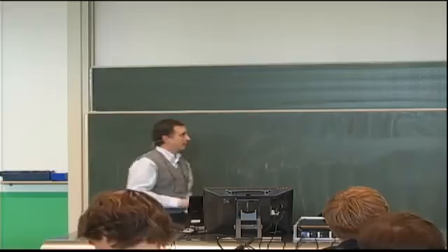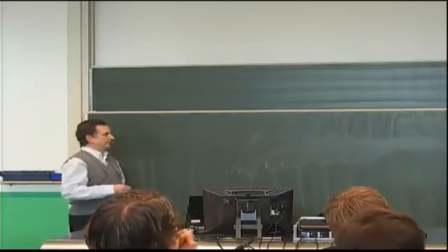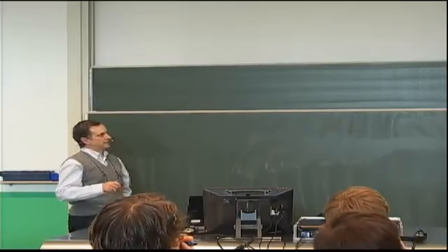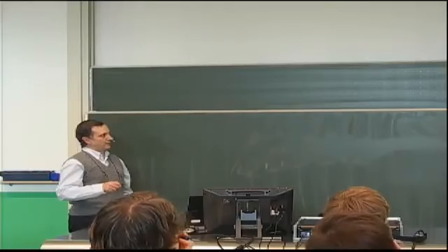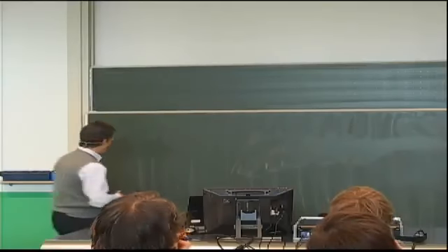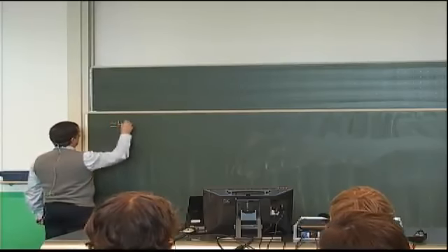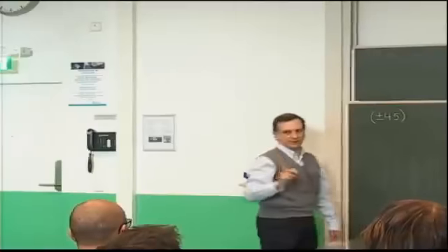So let's compare with the finite element model, which is the easiest in these cases. As a parenthesis, the laminate we're using has 4 plies of plus or minus 45. A designation with parentheses in this course would mean a fabric ply. So this is a fabric ply. It's a single ply, not 2 plies, 1 plus and 1 minus.